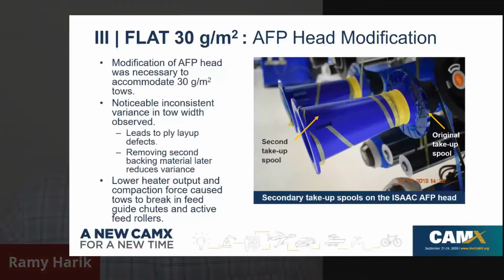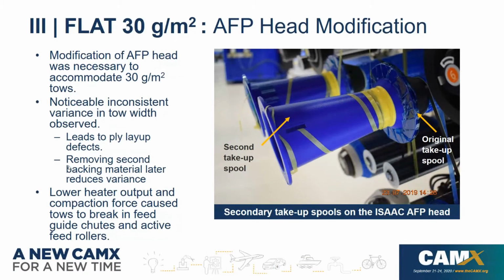So what we ended up doing is this exercise where we actually designed and 3D printed a second take-up spool. And this second take-up spool that we have done, you can see in here, this is the original take-up spool. And this second take-up spool actually takes the second backing tape. So the first one comes and rolls in here, and the second one is in here.